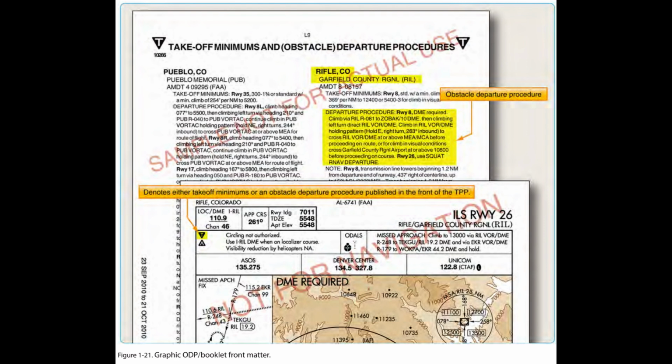ODP Flight Planning Considerations. ODPs are not assigned by ATC unless absolutely necessary to achieve aircraft separation. It is the pilot's responsibility to determine if there is an ODP published for that airport. If a Part 91 pilot is not given a clearance containing an ODP, SID, or radar vectors, and an ODP exists, compliance with such a procedure is the pilot's choice.